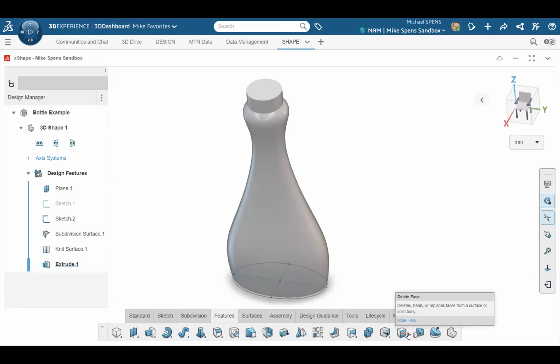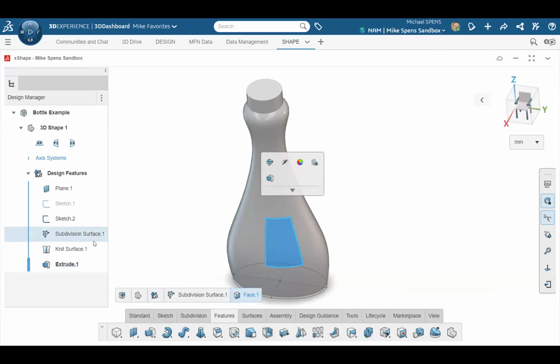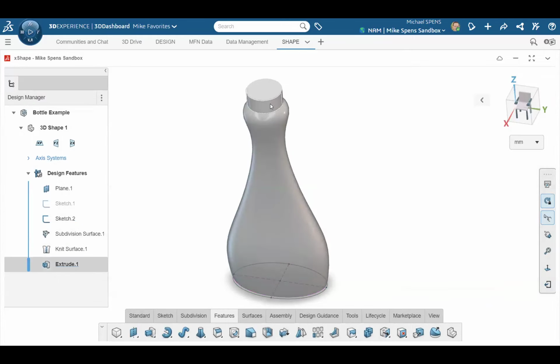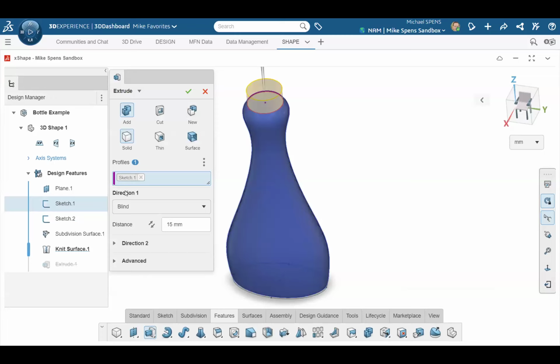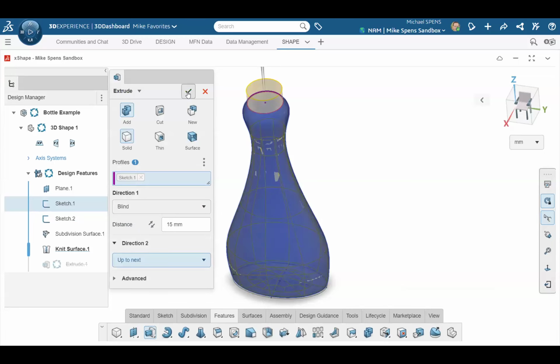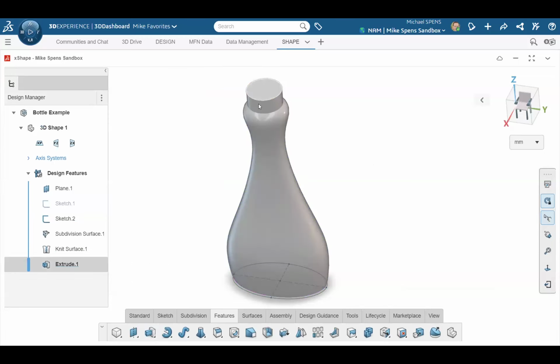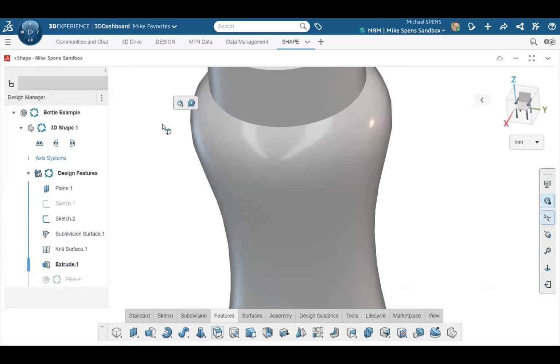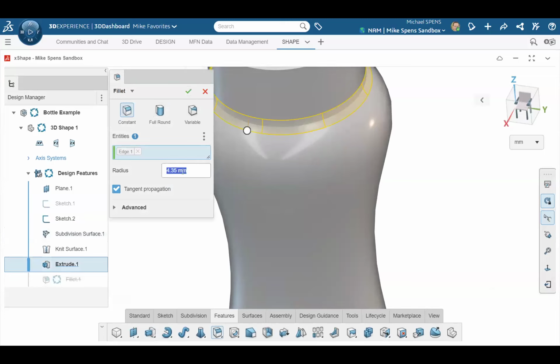So yeah, that workflow takes a couple extra steps certainly. But the changeability that you get with sub-D modeling, at least can you communicate? It's all SolidWorks, so you can reference this shape over into a SolidWorks model. And then later say, oh, I want to change this freeform shape between the neck and the base. So I go back here and change it, and I can have that reference show up in my SolidWorks model, right?